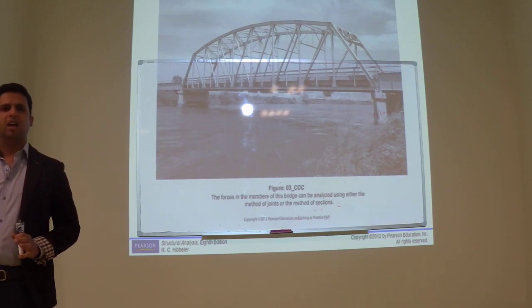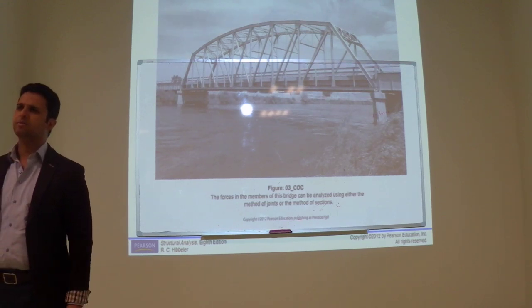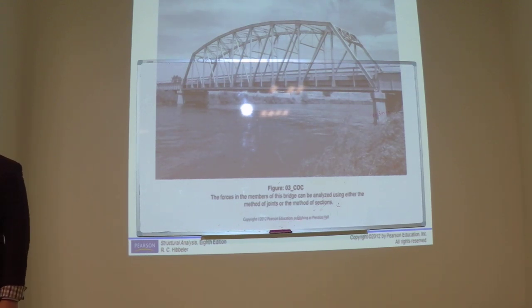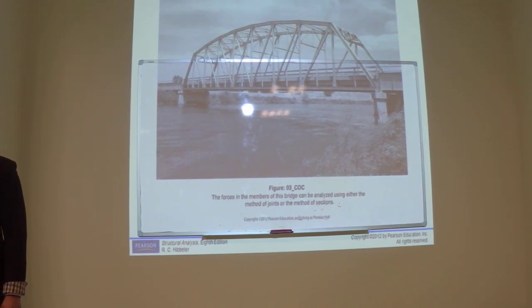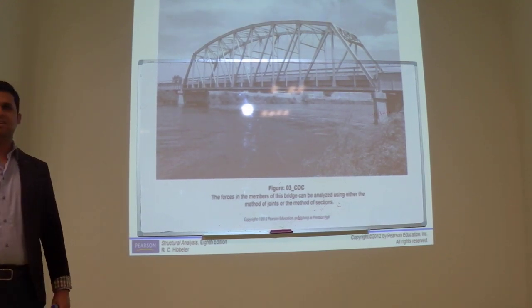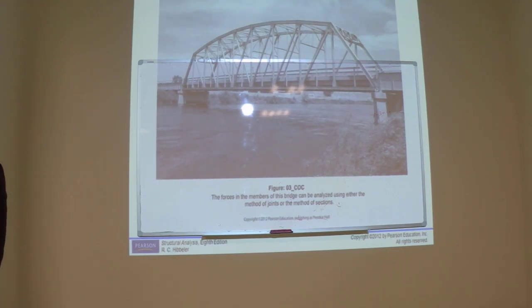Okay? Is it good to have no shear force and no bending moment, or is it bad? It's good, because the main failures we have in structures are due to shear. In beams, we have the major failures due to flexure or shear.